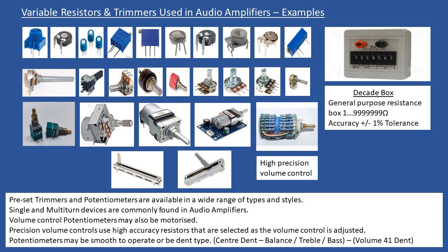Now, inside the motorized potentiometer, and you'll see this a bit later on when we show the internals of a potentiometer, typically on the back you will have a motor, and the motor is typically 5 volts, and then you have a motor control circuit, and from the infrared control circuit it will drive the motor in forward or reverse, and that mechanically rotates the potentiometer from the rear. There will be a gearbox, and that gearbox then rotates the potentiometer internally, and you physically see that when you're looking at the amplifier, because the volume control goes up and then goes down.